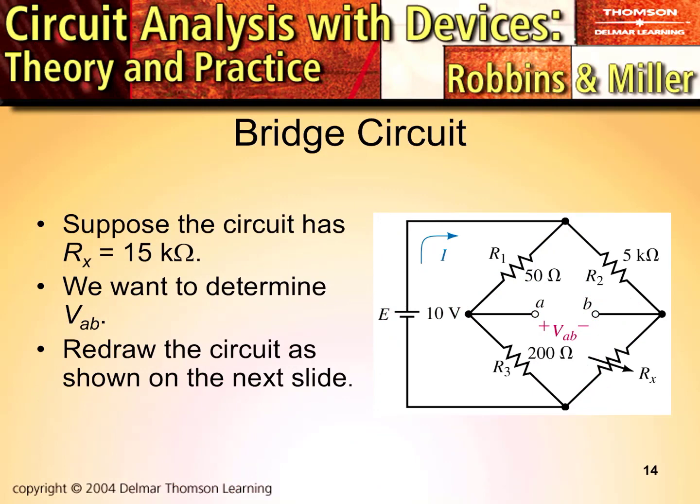This is actually not what's technically a bridge circuit. This is simply a series parallel circuit with two parallel connected series branches. The textbook's calling it a bridge circuit, but technically it's not a bridge circuit until you put a resistance right here. Once we have a resistance right here, this bridge resistor, this becomes a bridge.